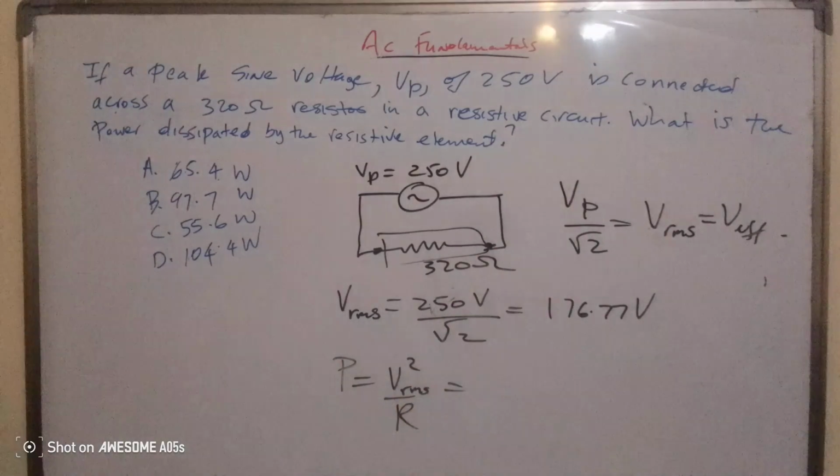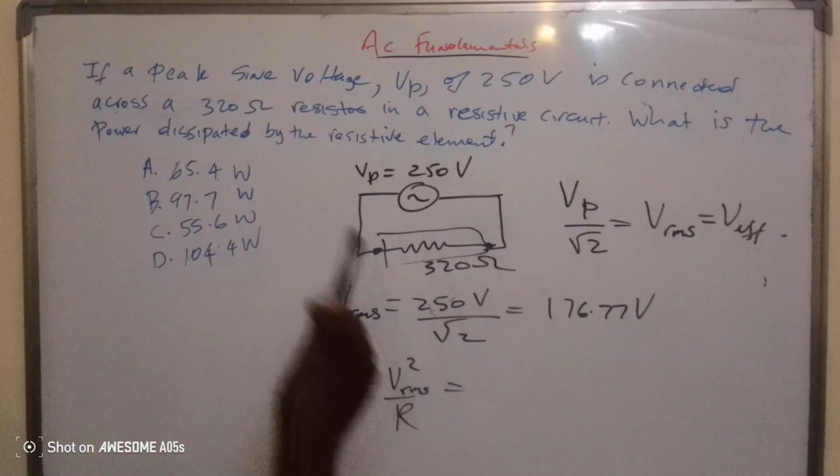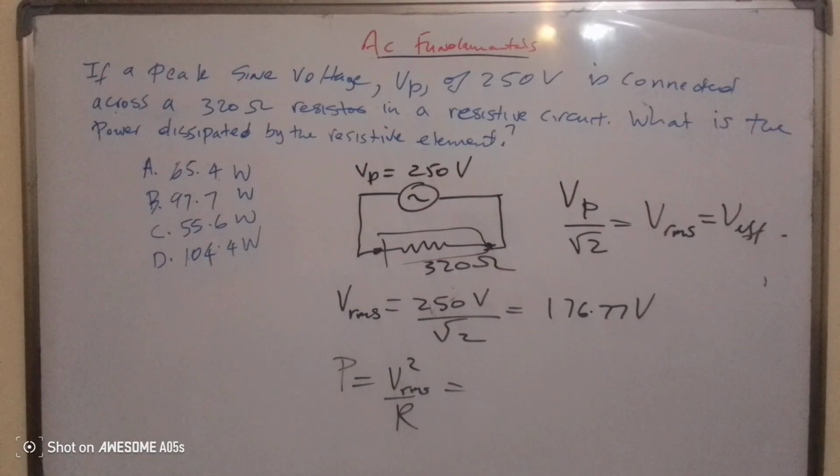That's why we get it from the peak voltage into the RMS voltage, because we're looking for the effective or the RMS voltage, which is useful power, like an average. Well, I would say the effective voltage, which is the RMS voltage. That's what you're gonna use for the power calculation, and you use V squared over R, right? So that V RMS squared over the resistive element.